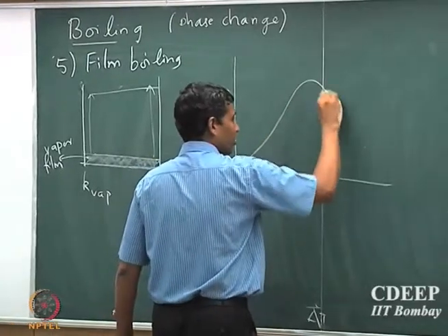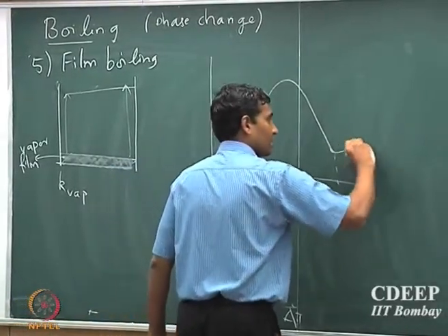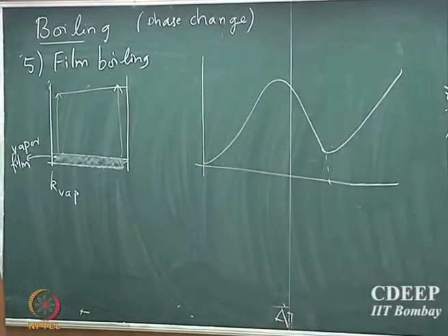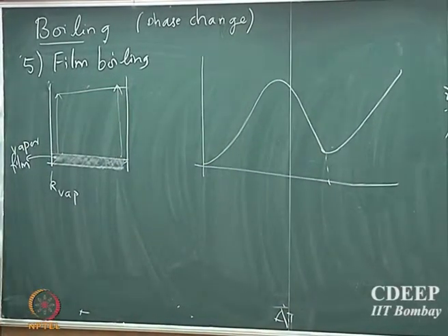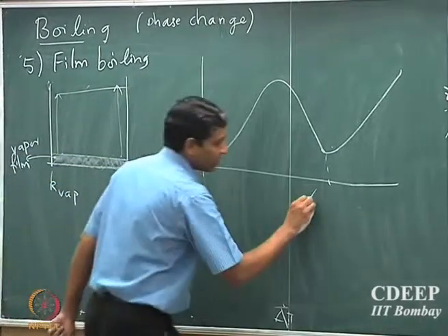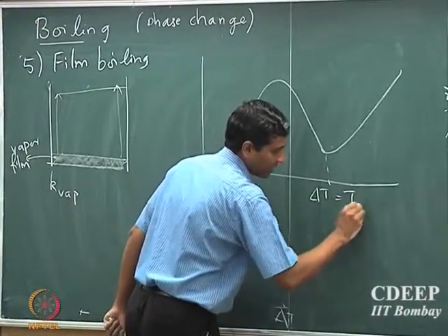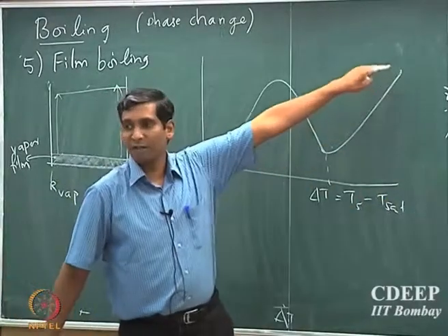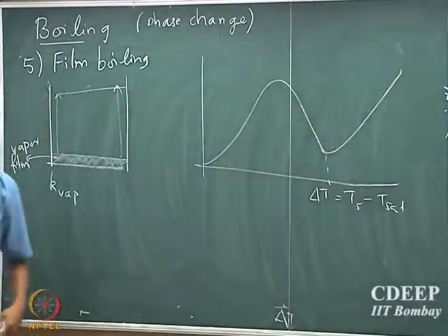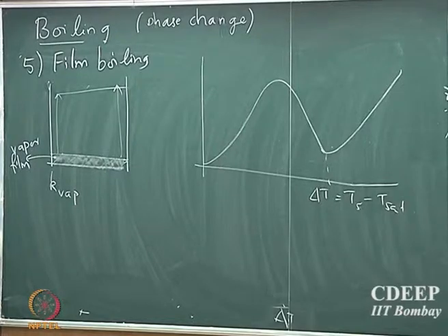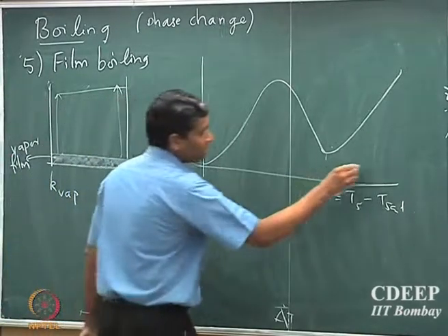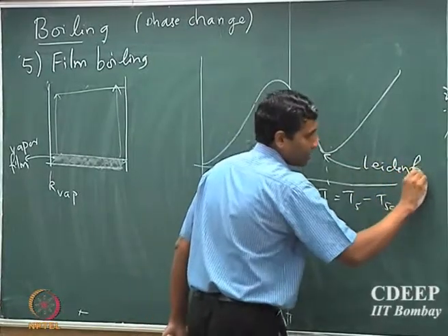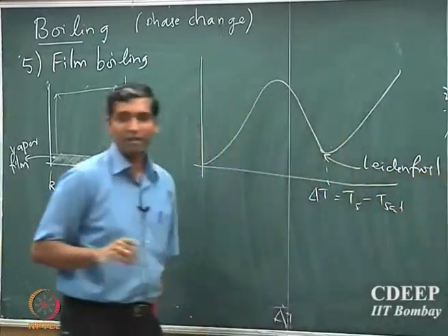And so the boiling curve at that stage would be, so now as you further increase the heat that is provided, so you increase the temperature difference, this is Ts minus Tsat, and therefore the net amount of flux of heat that is carried is going to increase with increase in the temperature difference. So, this bottom minima is called, just for historical purposes, the Leidenfrost point.